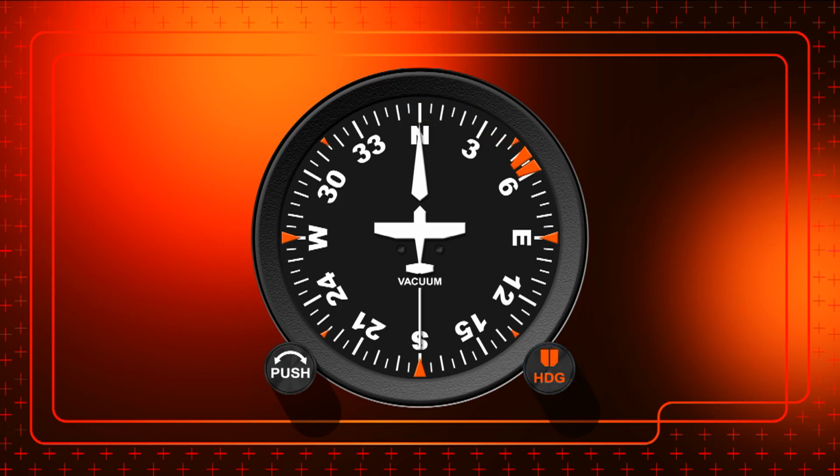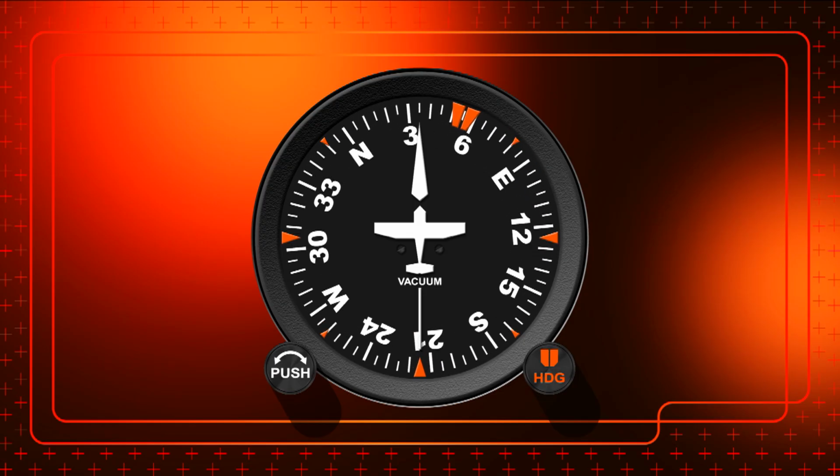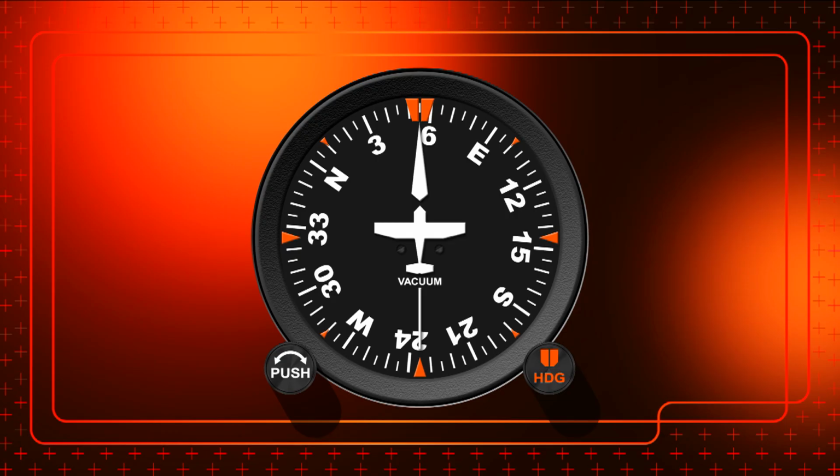then align the bug to 055 degrees on the compass rose, and then you will have a visual reference for where to turn to. This bug also works in conjunction with the autopilot system, but you can use it for either manual or automated flight via the autopilot system.